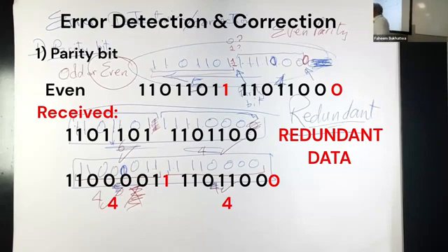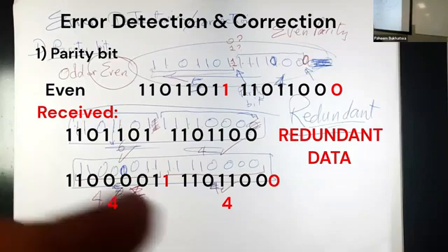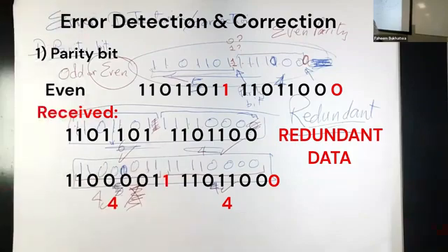So this error detection system has two major problems. It has a large amount of redundancy, and if you want to know exactly, it's 1 to 7, the ratio of redundant data to actual data, or 1 in 8, whichever one you say. And that's heavy by all standards. It's a lot of cost, heavy cost. And the second problem with this system is that it does not discover all errors. You need to know which errors it discovers and which errors it does not discover. So if there's only one bit in the frame that changes, that's okay, we'll definitely discover it.